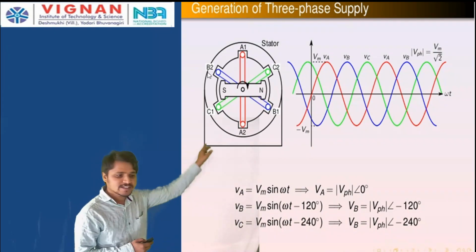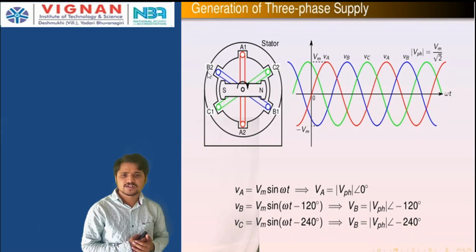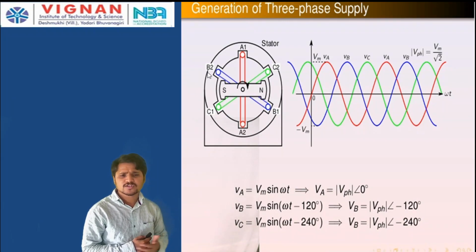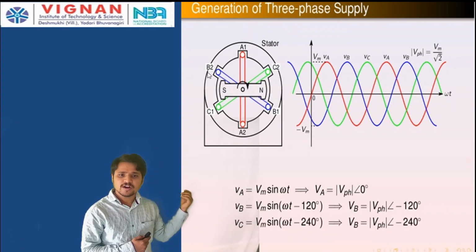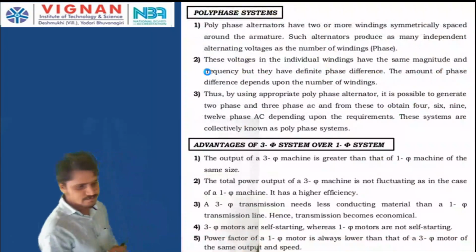So these are the three-phase waveforms. They show how the voltages are simultaneously generated and what the phase displacement is. This waveform is showing that the phase displacement between any two phase voltages is 120 degrees apart. If you say A phase, B phase, C phase, you can also say R phase, Y phase and B phase, that is red, yellow and blue, or any three colors.